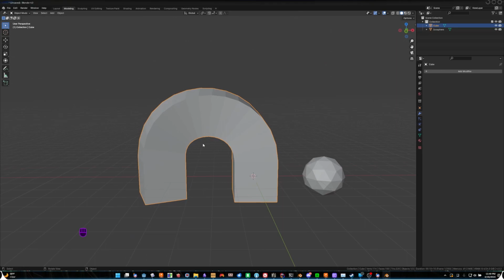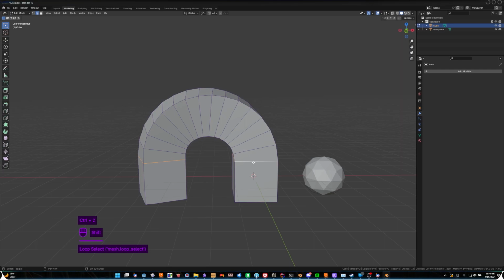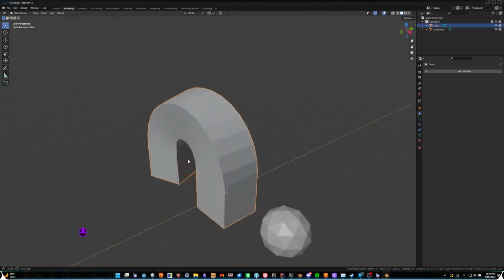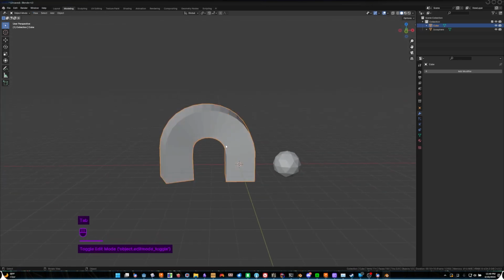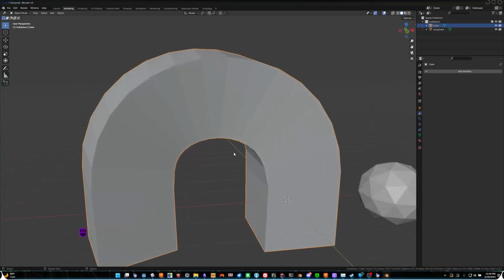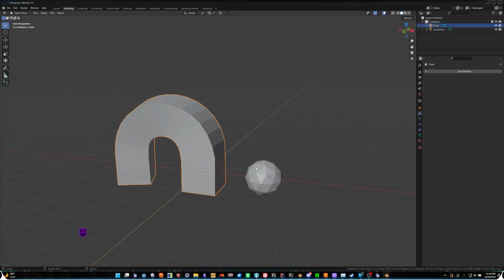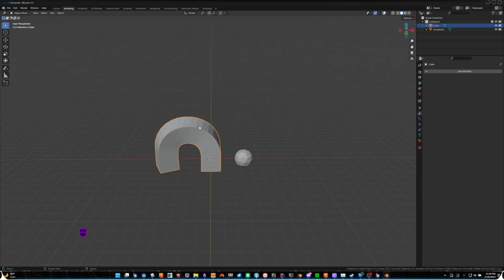In any case, now that we've applied our bridge, if you do run into a situation where your bridge between your edge loops is jacked up, just try selecting the edge loop that you originated. If you angle it towards the other, and hit R and rotate, you'll rotate from your current perspective. Rotate it towards the other edge loop and it will bridge better, trust me. But for now, you can tell that these are bridged by hovering over a vertex and hitting L. Now the whole thing is a linked mesh. It is one unified mesh now. So that's the difference between linked objects that share properties or meshes and a linked mesh.